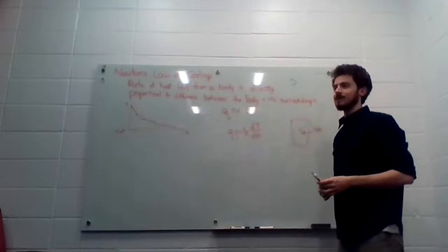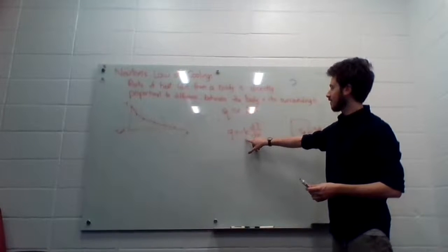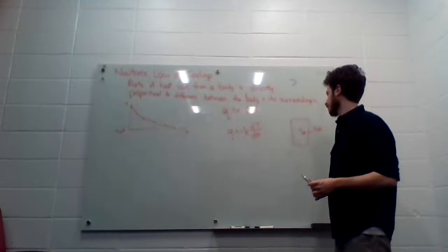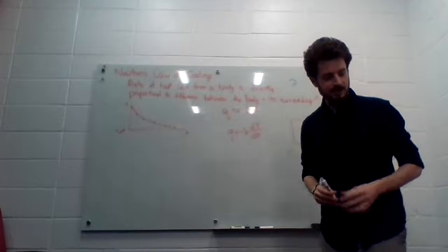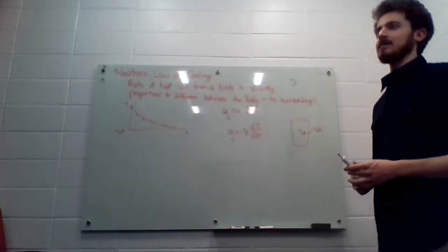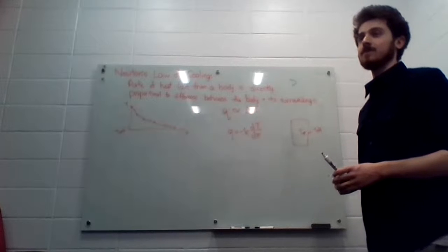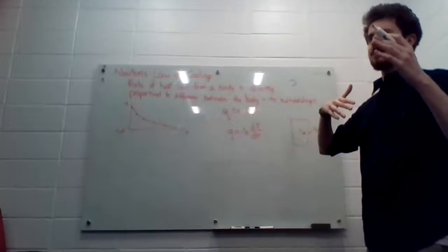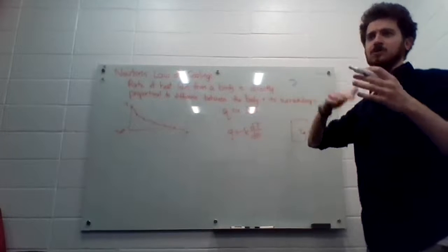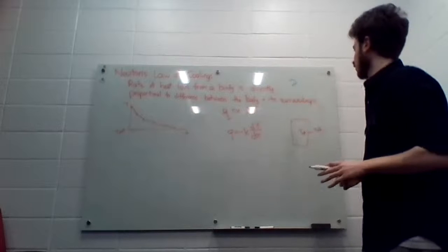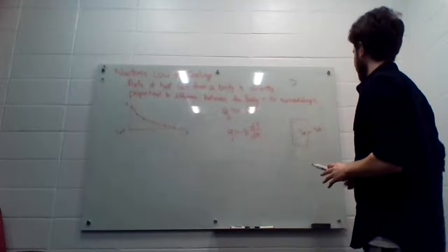It's why thermal conductivity, if you conventionally have it as a positive sign, you need a negative in Fourier's law. Okay, so that's Fourier's law. It's linear. That's kind of the big thing that's nice, and it makes a lot of stuff in heat transfer easier. I know with like a lot of electromagnetic stuff, things are quadratic. So as you move further away from an object, things change quadratically. But heat transfer, that's not the case.